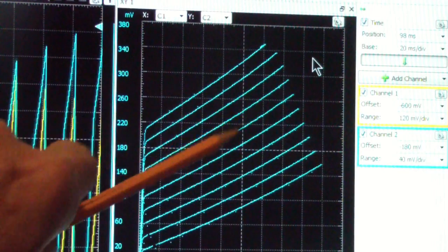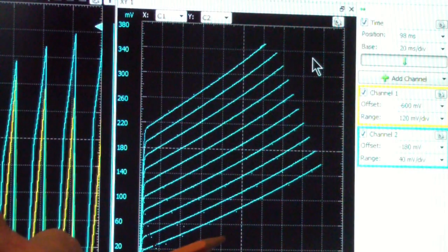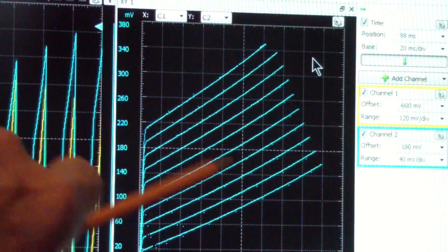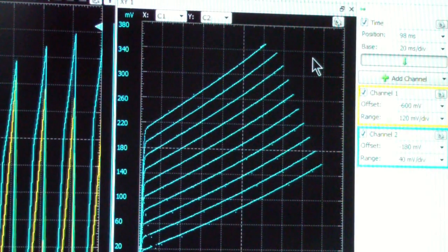Earlier, if you recall from some of the diagrams, there were a series of dots all over the screen from time to time. That's actually the retrace of the sweep. So what we've done is we've cleaned that up by using a sawtooth wave.